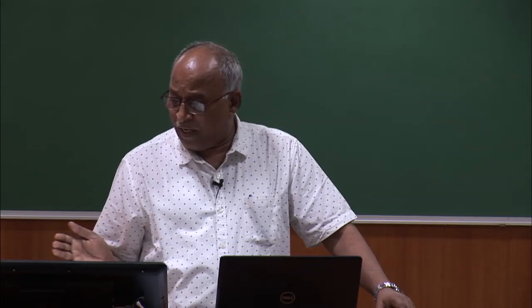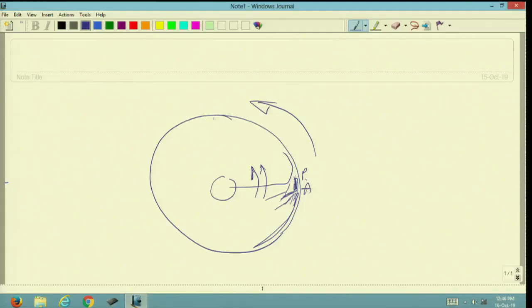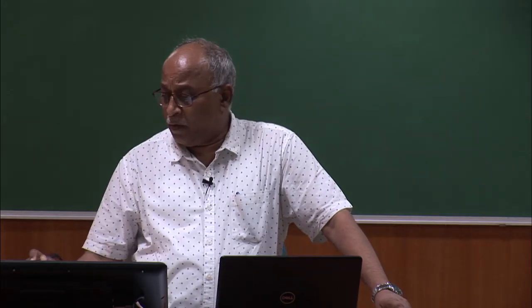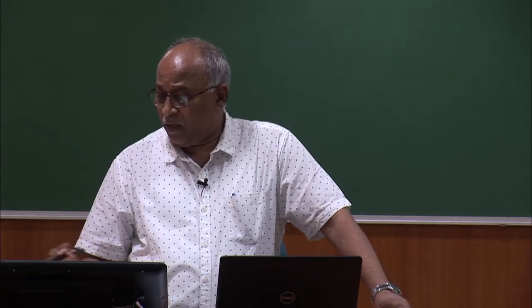Then after that a new layer again is going to be formed, right. So, the first time you have one layer, then the second time, you have one layer which is formed, and the new one will be starting just above that. And as the rotor is rotating, this will keep depositing on it. So, layer by layer it will continue like this, right, and that is why it is called a cyclic aggregation process. So, you have a tapering kind of thing, right.